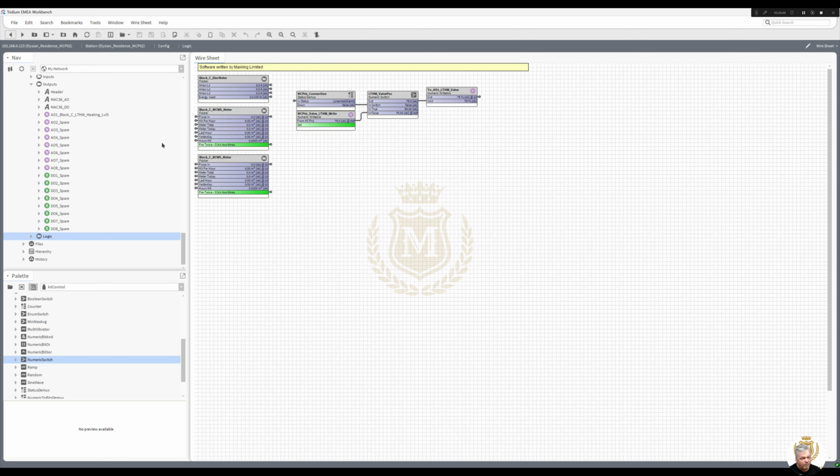And then I presume we can play a little bit clever and we could put the fire alarm into this. So that if a fire alarm goes off on the panel, we write that straight to 0, which would just be another numeric switch.